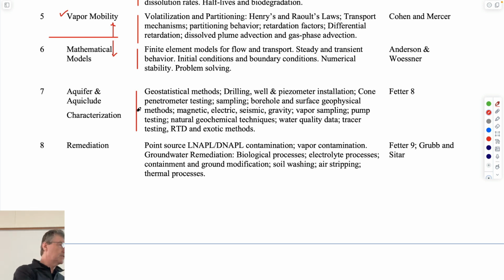You have a spill, this is the stratigraphy, these are the characteristics of the materials that it's spilt into. And this is the geometry of the in situ fluids. This is the geometry of the plume that has come from those. And so with that information, you have to make some design of how you might remediate it. But the question is, how do you know what that initial picture is before you go in there?